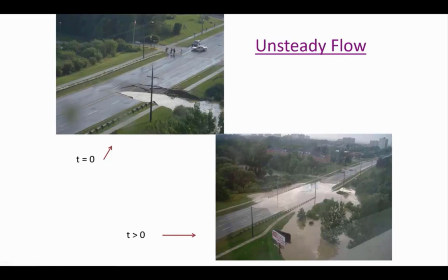But when there was a lot of water flowing through this creek, the water level rose on the upstream end of the creek, and that created a seeping pressure that caused a scour and piping of the soil particles that were around the culvert. And so they packed soil around the culvert, and of course water was flowing through the opening of the culvert, but water was also seeping through the soil itself, and that can undermine the soil and reduce its strength. And so that's kind of what happened here: that culvert eventually failed and collapsed in on itself. And so that's an example of unsteady flow.